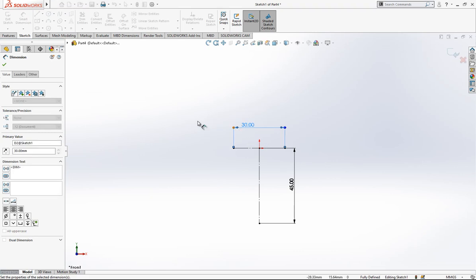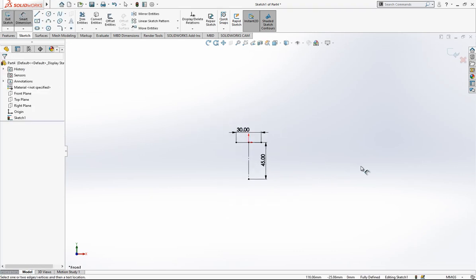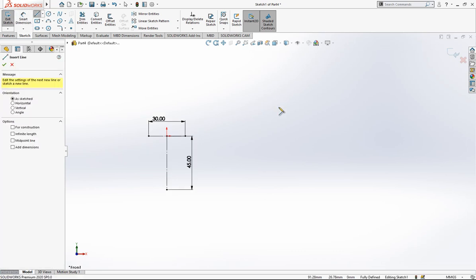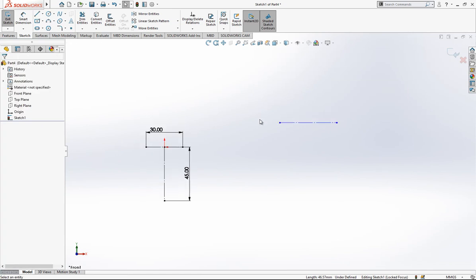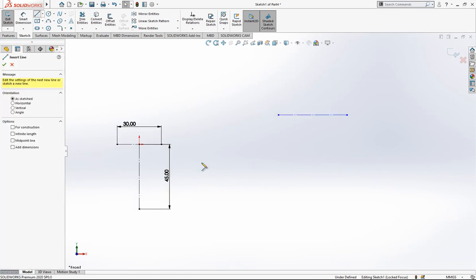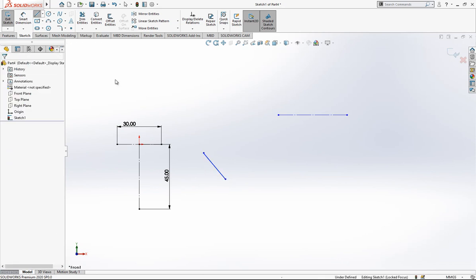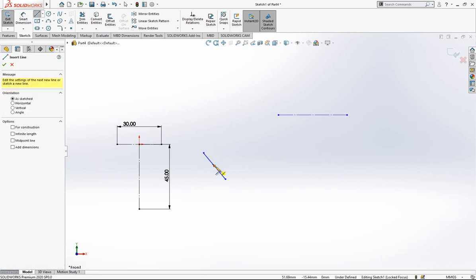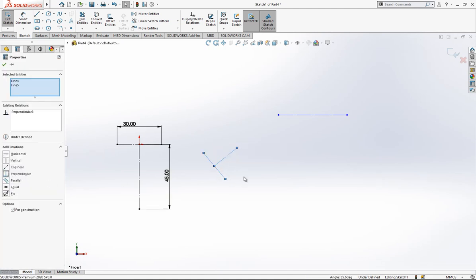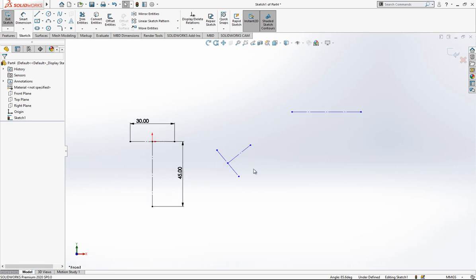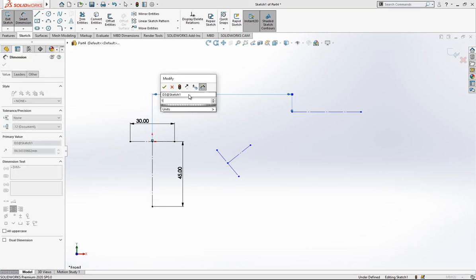After I place here a 130mm diameter, there will be a section here, and let's also determine the other sections where our other profiles will be placed. I place here also. I made it construction geometry, and I create here a perpendicular relationship. This will be from here in the point